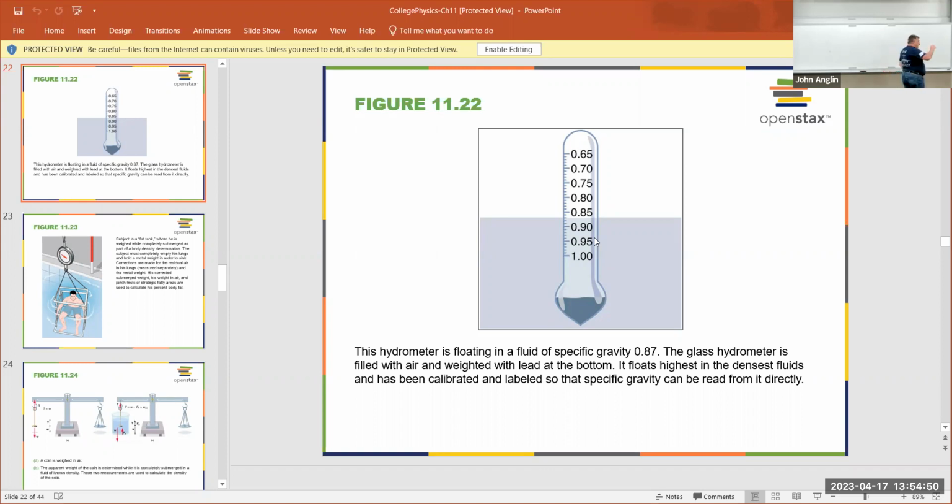So you measure the density of effectively the sugar fluid prior to throwing in the yeast, and you wait a few weeks and you come back and you measure that specific gravity again. There's a change in density there. That's what your specific gravity tells you. You throw in this little formula and that tells you what your alcohol by volume is. It tells you if you've made a 3% day drinking beer, or if you've made a 15% wake up in your backyard Monday morning wondering what happened beer.